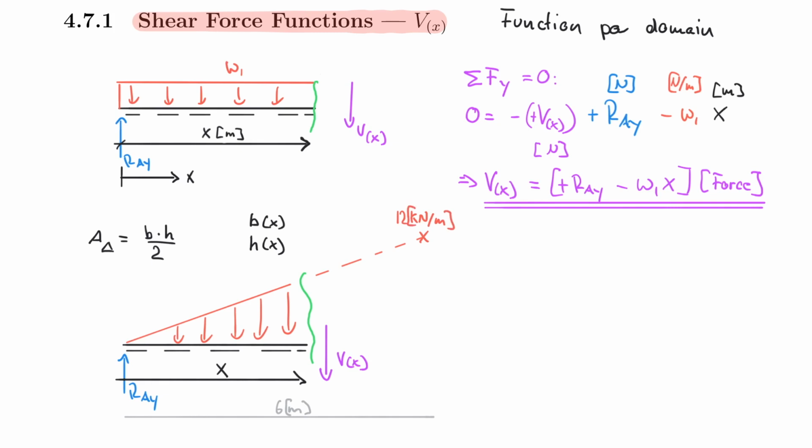And so what that means is that our beam actually extends past the cut and of course may even extend past the triangle, but our triangular load case may be over at this location, where then here we have the 6 meters. And so that means we can now calculate the slope of this line, and the slope is really nothing else than the rise over the run, right? So we have, in this case, a slope of 2. So let's actually document this. Slope is equal to 12 over 6 in our case, which is 2.